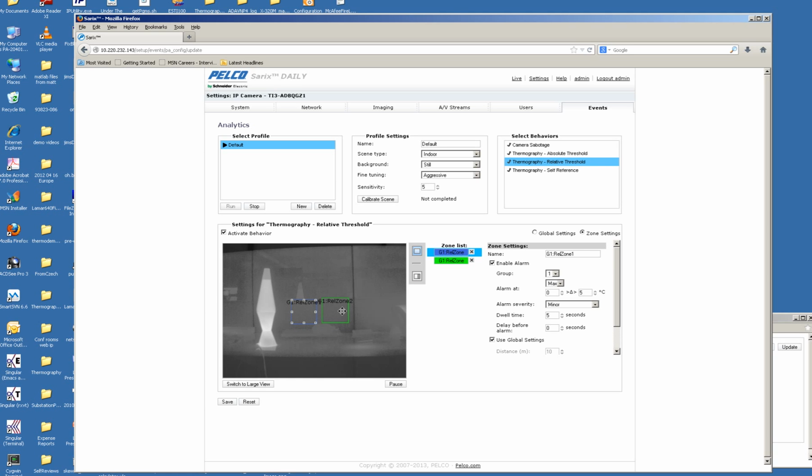If the temperature range of all the zones has become greater than a certain threshold, a certain amount, then an alarm will trigger. The idea is that for all the equipment that are similar in temperature, they can all rise and lower at the same time. But it's not okay for some piece of the equipment not rising or not lowering to create a large temperature delta between them.